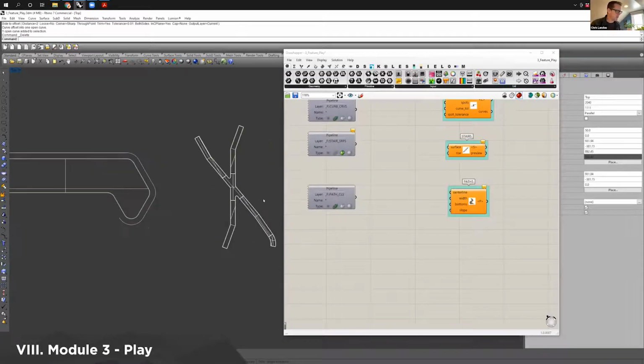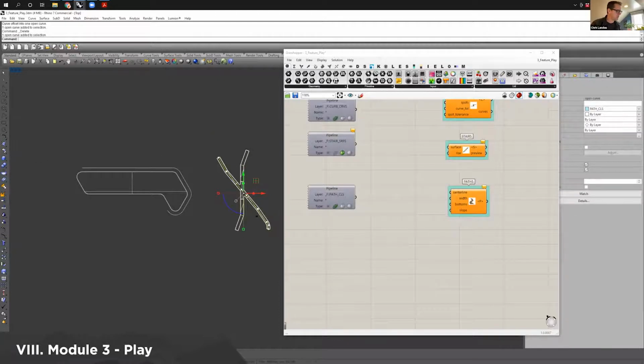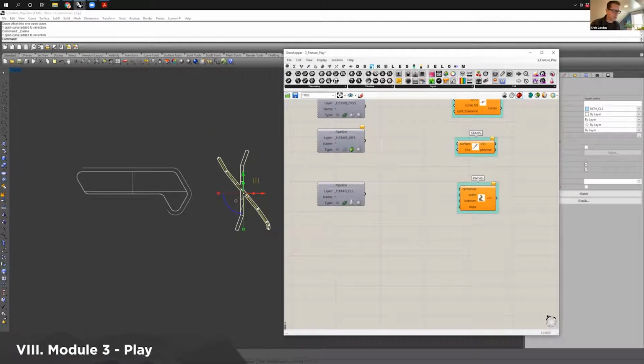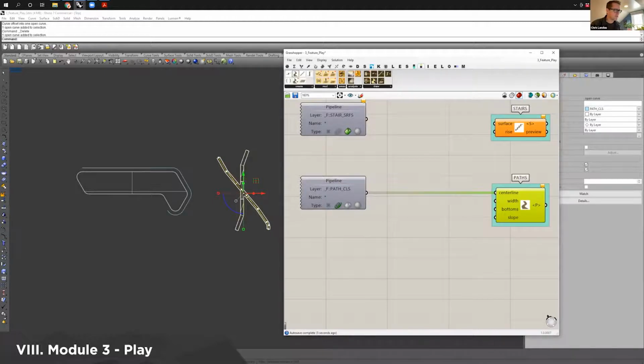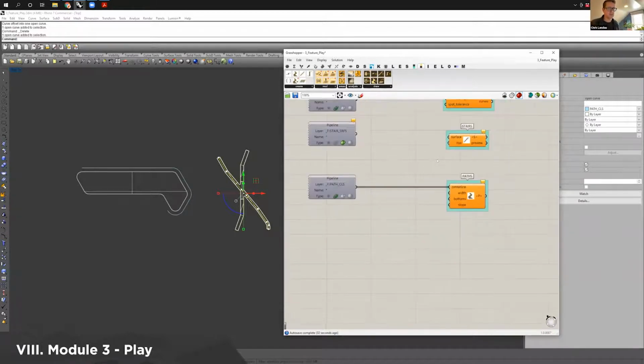And that's how we created these curves for our center lines for paths. So that's step one. We have these path CLs, and we'll plug that into our paths component here. Again, all of these components are available here to create them under this tab, create curves, all the main things you would create in the beginning, and then all the draw stuff is here at the end. And then we have our mods for topo and features in the middle, and some analysis and stuff as well. Analysis should probably come last, but actually analysis gets used in the process, which is part of why it's not last, I guess.